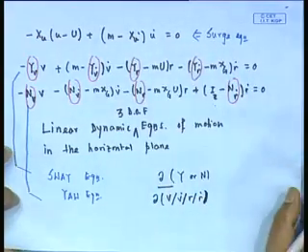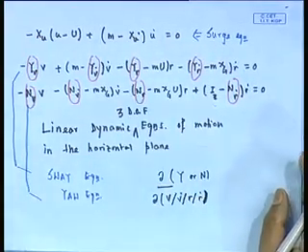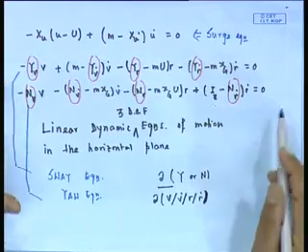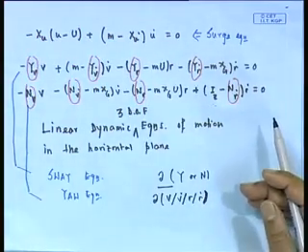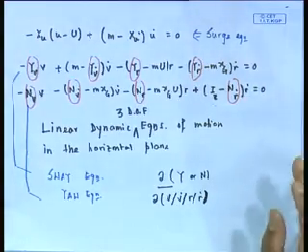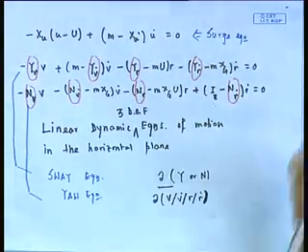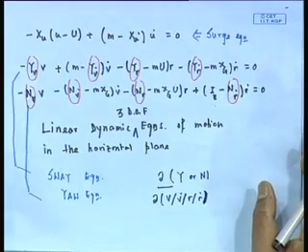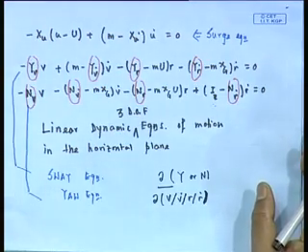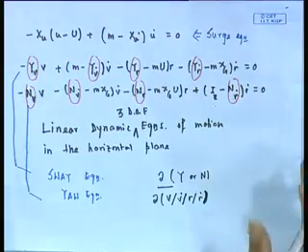That means the unknown hydrodynamic forces that have been created on the hull are fully represented by these 8 terms in this equation of motion. Of course, if you take a more complex equation, it will be more, but to start with, the basic minimum unknown becomes these 8, provided there is no rudder action. I have not taken rudder action, rudder is not working, it is only a bare hull.